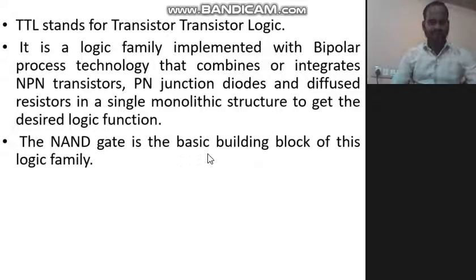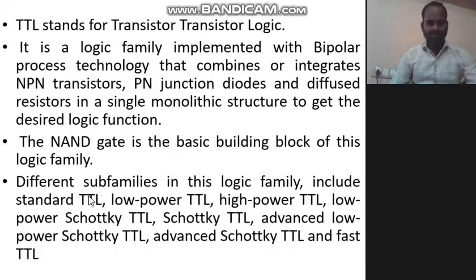The NAND gate is the basic building block of this logic family. The different subfamilies in this logic family include standard TTL, low power TTL, high power TTL, low power Schottky TTL, advanced low power Schottky TTL, advanced Schottky TTL, and fast TTL. These are the different logic families inside this TTL logic family.